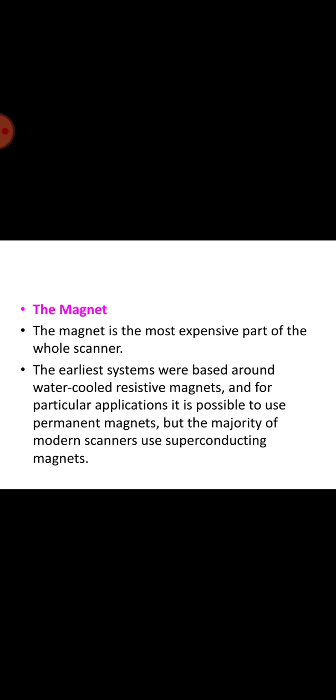These magnets utilize the property of certain materials which lose their electrical resistance fully below a specific temperature. The commonly used superconducting material is niobium titanium alloy, in which the transition temperature lies at 9 Kelvin. In order to prevent superconductivity from being destroyed by external magnetic field or the current passing through the conductors, these conductors must be cooled to a temperature significantly below this point, at least to half of the transition temperature. Therefore, superconducting magnet coils are cooled with liquid helium, which boils at a temperature of 4.2 Kelvin.